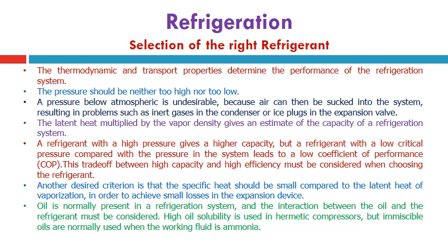So when any leakage happens, air goes inside the cycle and damages its performance rapidly, and ice forms inside the cycle within the working fluid, plugs the piping and the condenser, and makes the cycle stop.